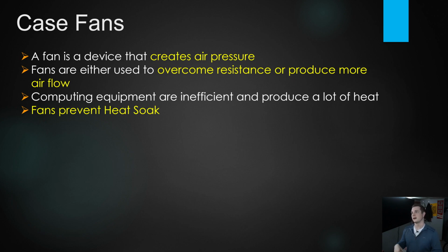If we have very low resistance and we just need to create a bunch of airflow, we can use bigger fans to do so. Now, obviously, the fans need to fit, so your server environments are going to be very limited in that respect. Your 4U case can fit a 120 millimeter fan, which is commonly found on your consumer cases, but it's not going to fit 140. And then if you go any smaller than a 4U case, then you're directly into server environments. You might be able to find an 80 mil consumer fan, but more than likely you're going to have to do a server fan, which is quite loud, but they also spin quite high to produce a large amount of airflow.